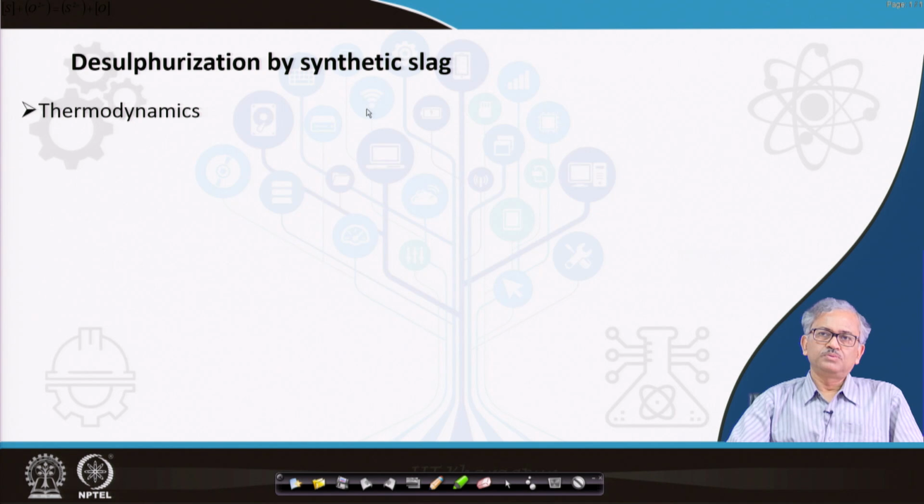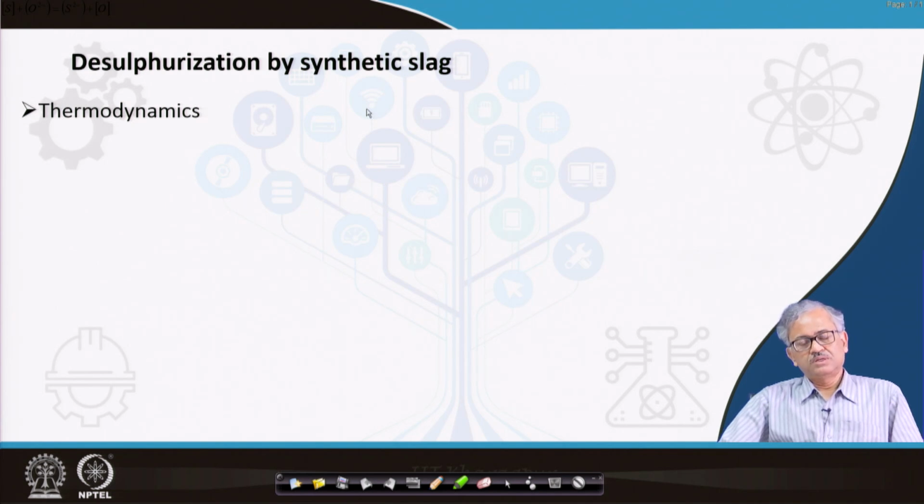Okay. So, after you prepare the steel, as you know, sulfur can only be controlled in the blast furnace operation, because there we have a basic and reducing slag. After that, in steel making, you do not have much control. Effectively, we cannot reduce any amount of sulfur. So, sometimes, to reduce the load of the blast furnace, desulfurization is carried out in between the blast furnace and the LD process. That is called external desulfurization. This to some extent reduces the load of the blast furnace.